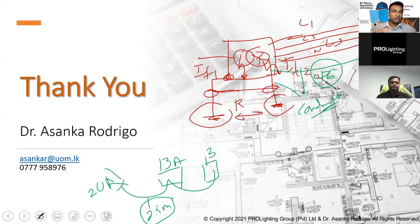So this earth electrode resistance matters. Even when you carefully read the standard, you will understand that the earth electrode resistance values are specified for a TT system, not the TN system. TN system, you don't care. Why does earth electrode resistance not matter? Because your earth fault current will not go to the earth electrode, since there is a conductive path for the earth fault current. What we call IG, the ground current, will not be there in the TN system, so you don't have to worry about your earth electrode resistance in a TN system.